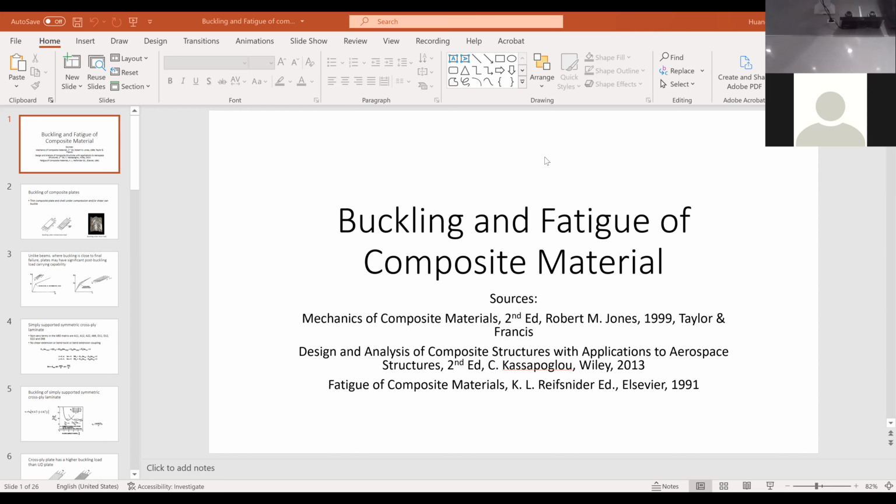Okay, so you all have completed maybe 80-90% of the code, which is the CLT calculation. You want to continue to add in the hydrothermal functionality, and then we're gonna have a final project user code to do a failure sequence simulation that basically ties together the failure criteria we learned to simulate a sequence of failure from first ply failure, second ply failure to final failure. You're gonna reproduce the loading sequence that leads to final failure. That will be the final thing.